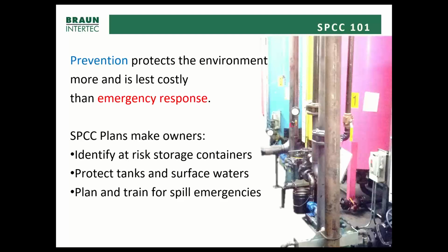So as we walk folks through the SPCC plan preparation, we're working with the owners to identify your at-risk storage containers. You have to do a comprehensive inventory of your entire facility. We also want to make sure we're keying in on the storage containers that may be in at-risk situations, whether they're close to a floor drain or close to a stormwater receptor and may not have adequate containment. And we also want to make sure that we are protecting both our tanks from damage during delivery and our surface waters from accidental releases.